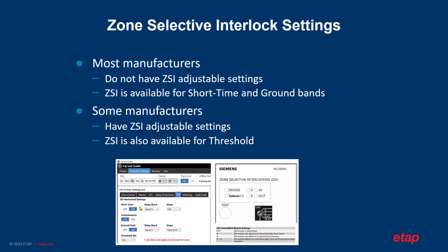And you have adjustable capabilities for short time delay and slope, for ground delay and slope, and also you can enable the threshold for ZSI short time and instantaneous.